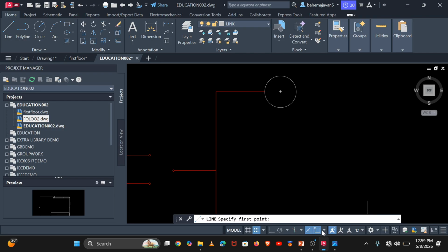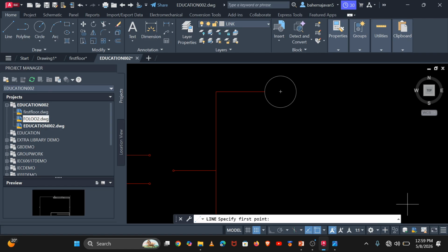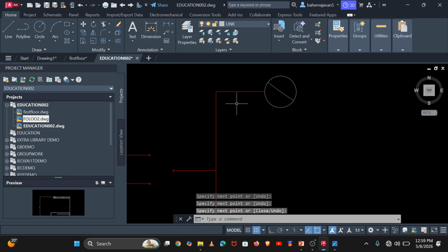And by the lines, when you want to draw a line in a circular thing, you first have to understand this part where I'm going to show you this. This is called the nearest. It is a kind of point that must be on the drawing so that you can draw anywhere else you want. When I click so that it becomes on like this, and then I must search wherever I want, and this line must pass through the center, and I search so that this line somehow forms an angle of 80 like this, and then click enter.